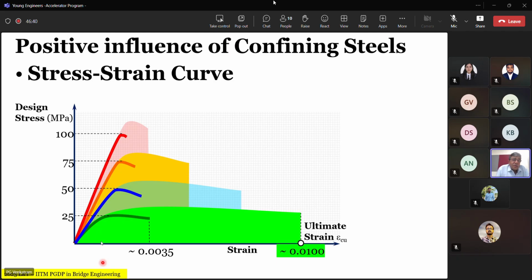Okay, so in the last few classes, I have been saying that as long as you are designing reinforced concrete structures, you must use the lowest grade of steel possible. Of course, since in India they have stopped manufacturing 415 grade steel, you end up having to use 500, but that's still better than going and using MMFX bars of 1000 MPa yield strength all over the place.